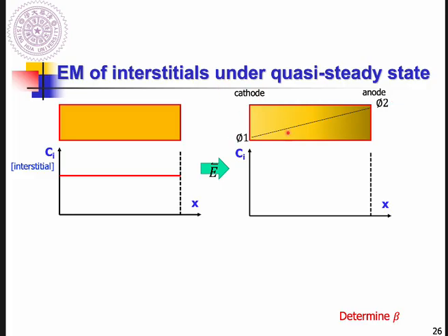And we have an electrical potential gradient going this way. So we have a current going to your left-hand side. Okay? So the electron flow will go to the right-hand side because it's the opposite direction of the current. As long as the electron flow is high enough, it will push these interstitial atoms.